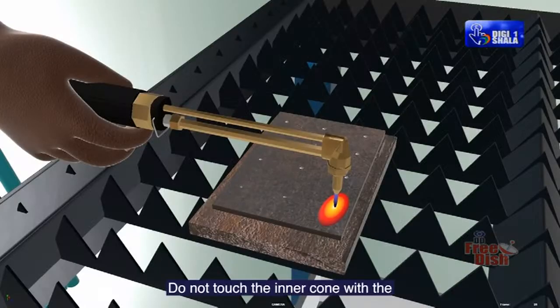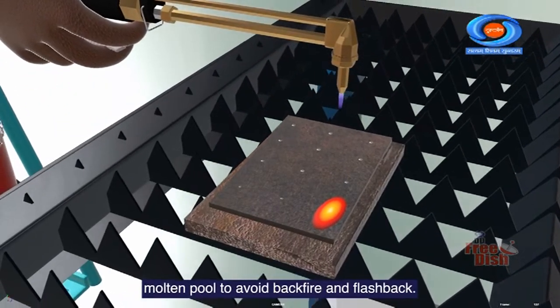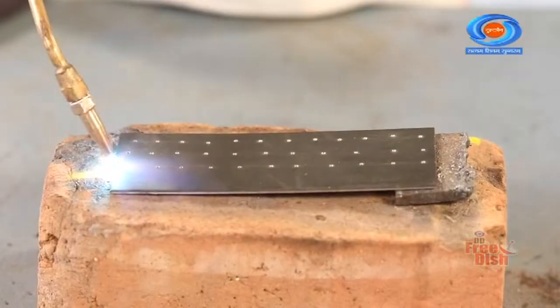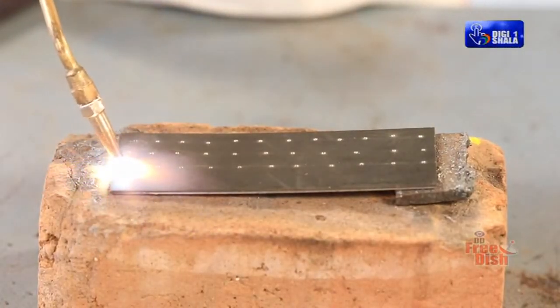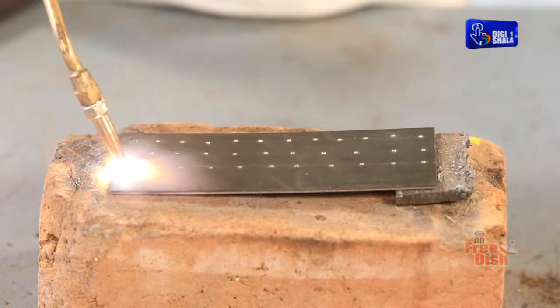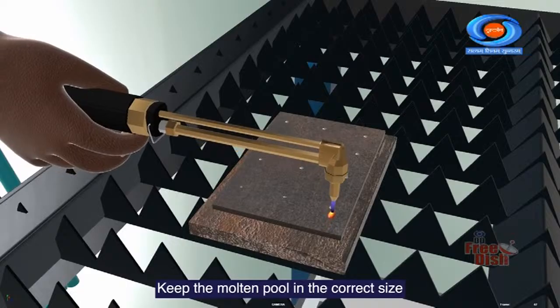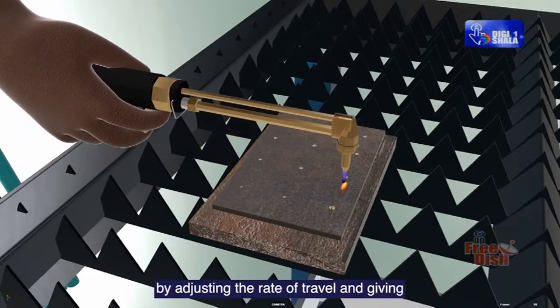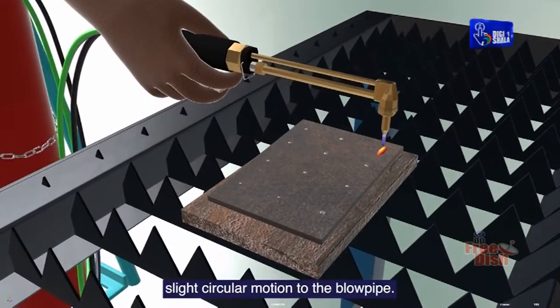Do not touch the inner cone with the molten pool to avoid backfire and flashback. Keep the molten pool in the correct size by adjusting the rate of travel and giving slight circular motion to the blowpipe.